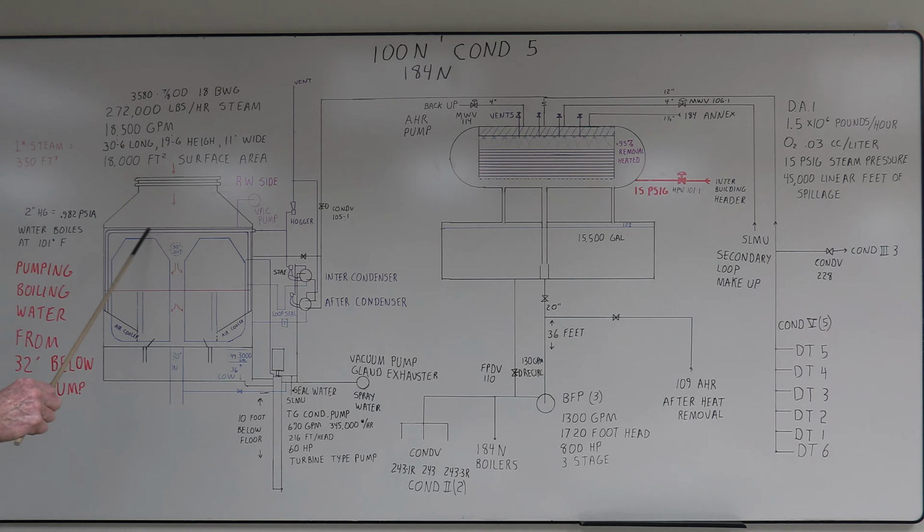They had a vacuum pump on the water box. You have a tendency to build up air in here as the water is under lower pressure. This outlet went to seal well number 2. So it's actually pulling a siphon effect on this, so the pressure is a little bit less than atmospheric. That just increases the efficiency of the cooling water system. So your circ water pumps don't have to pump water up quite as high.